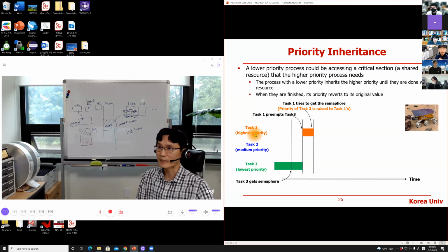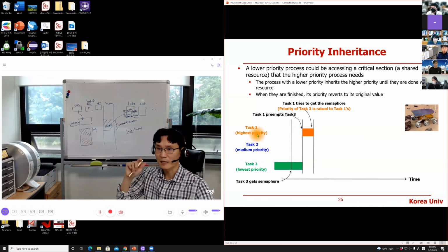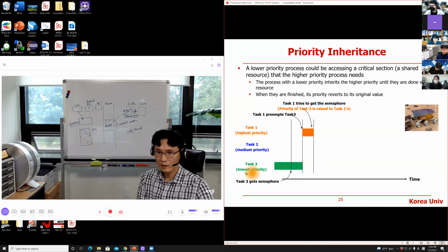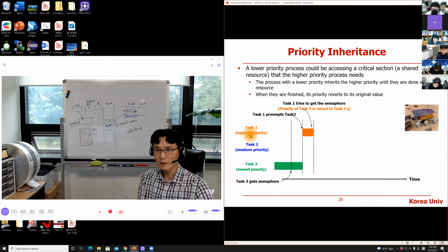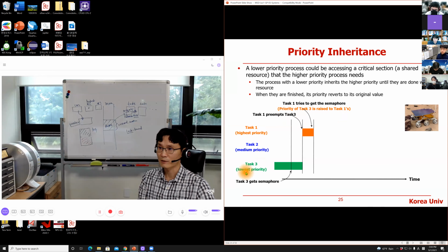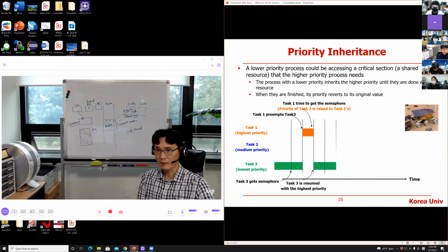Okay, priority inheritance. It is inheriting. The OS is promoting this guy's priority, the lowest priority, to that priority, the highest priority. It inherits its priority. So now, look at this. The priority of task 3 is raised to that of task 1. Now this guy has the highest priority.